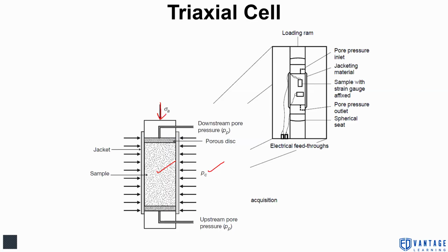So generally in triaxial test, we have two different tests. One is conventional, one is true. In conventional, as I've already told you, in subsurface, in geobodies, we have three stresses: sigma V, sigma H max, and sigma H min, right? So these three stresses can be artificially mimicked in triaxial setup. How? In TTT, true triaxial test.